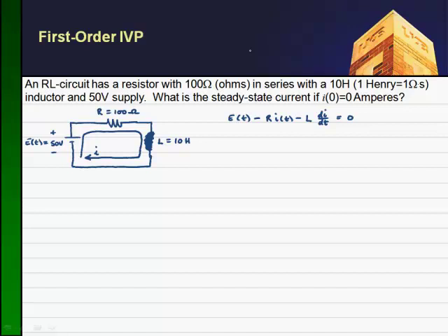So an inductor always works by opposing a changing current. Essentially, if you use your right hand rule and follow the direction of the current, it'll set up a magnetic field which will oppose a changing current. Since this is a DC source, it's probably only going to turn on once we flip the switch, and then immediately the current should rise.